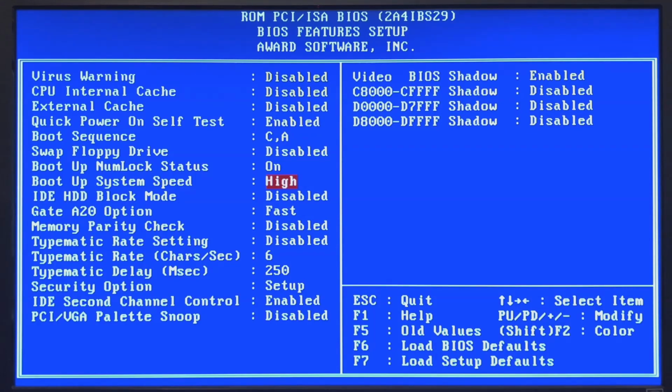As with my 486 machine, the clock generator actually generates a 5 MHz clock with a 2 MHz crystal and a 2.5 multiplier. But then due to this deturbo function, the effective clock is something like 2.5 MHz. Now with the same crystal I can easily go to 3, 3.33, 4, 5 or 6 MHz just by changing some jumpers. So overall very nice.